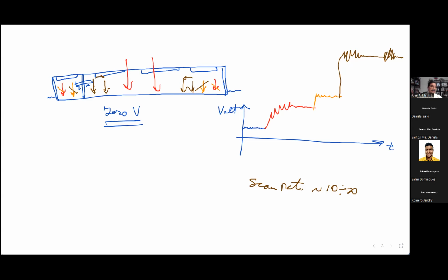I was thinking that it is possible that we could make another cut in the central part and try to measure, instead of shear force, bending moment. So we could measure a shear force at about 1/4 of the length, and in the central part we would measure bending moment. But that's for the future. Let's see what happens in this case.